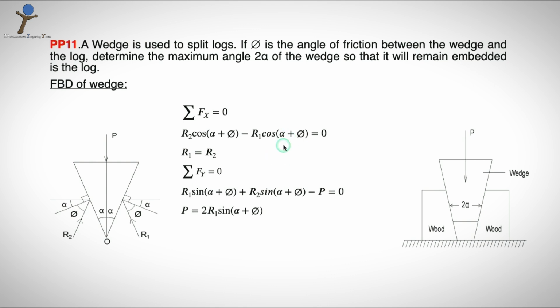In the first stage, you determine the applied force P if the reaction is a known value. In the second stage, the wedge has to be driven and the force is removed to determine the angle alpha. So let us start with the first phase of the problem.